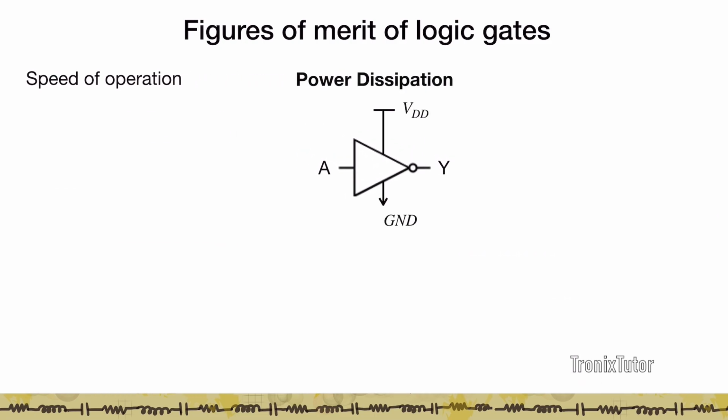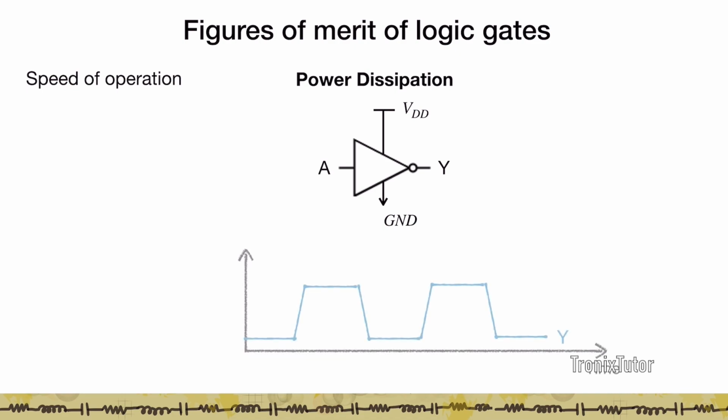Now the other figure of merit for the logic gate is the power dissipation. So remember, every time this gate is giving you an operation or an output, it is burning power. We spoke about two important properties of the digital gate: one is noise immunity and one is restoration. Digital signal restoration essentially means that power is consumed to ensure that the output behaves better than the input.